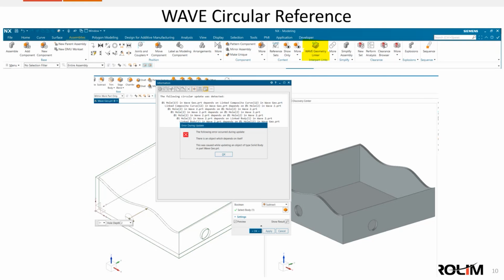It also happens on the assembly side if you have constraints. So you have a sub-assembly, and let's say, for example, you have a wire diagram or wire harness going on. You have a component within that wire harness, a connector, that is used to create a link. They go to the parent file, and then try to take that connector piece and constrain it to something else. It's going to tell you can't do it. You get a circular reference. It's just a big loop. Just think of it as a loop. All right.